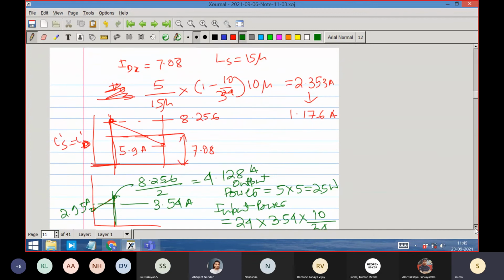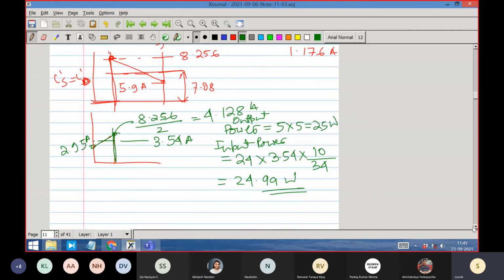No, I didn't say the net change in inductor current should be 0. I said the net change in flux should be 0. That is applicable here as well. The flux is L1 I1 and L2 I2 together, so everything together. Inductor current is not such an important thing when this is a coupled inductor. The flux is changing the same way.